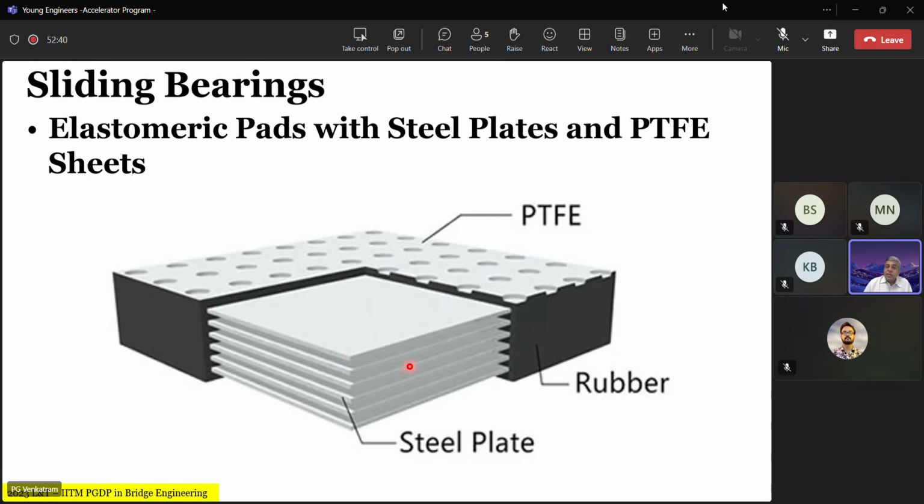As I've told you earlier, larger shear displacement requires larger rubber thickness, while volumetric changes are very small. So if you are transmitting practically only vertical load, then the thickness of the whole bearing can be reduced a lot. But obviously, if you end up having one end sliding, the other one has to take all the longitudinal forces. So you need another mechanism there. Typically in all these things, there is no free meal, as they say. You take an advantage in one place, you tend to pay a price in other places.